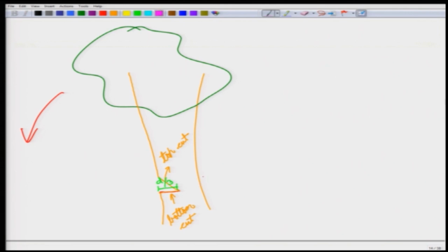So, you start cutting it, typically at a slightly higher location. You will start cutting from here, and you will probably make use of a saw to make the back cut. Typically, we avoid the use of axes, we use saws, because you have to cut down the fibers one by one, and these fibers are already in a stretched position. Consider that you have a very large number of strings that are kept taut, and you are slowly cutting the strings one by one, so that this tree will now lose its rigidity and it will start falling.